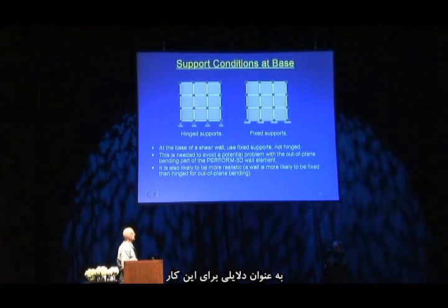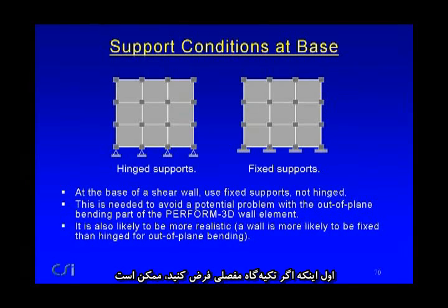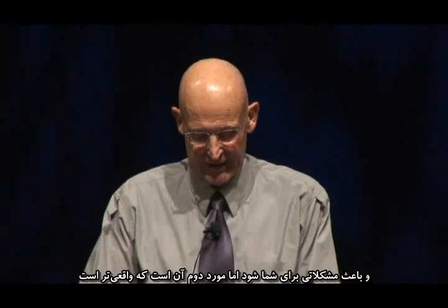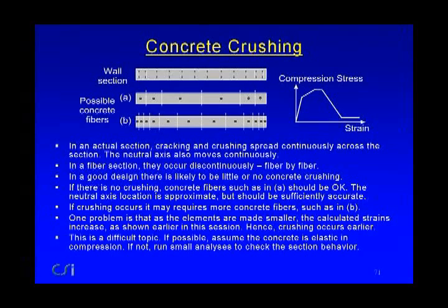And there's a couple of reasons for that. Firstly, there's a bit of a problem with the Perform 3D wall element, and if you do assume hinge support, sometimes it can give you trouble. But secondly, it's probably more realistic.